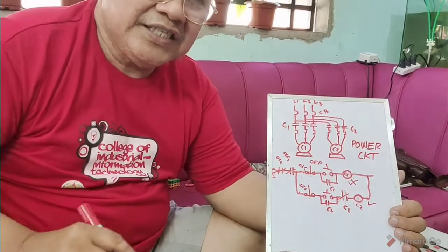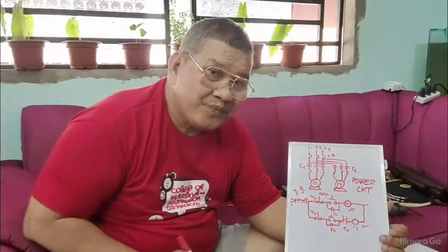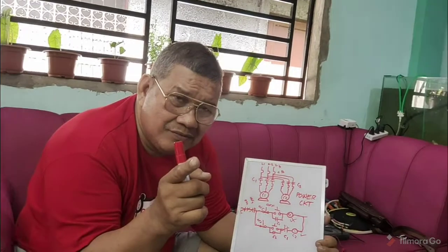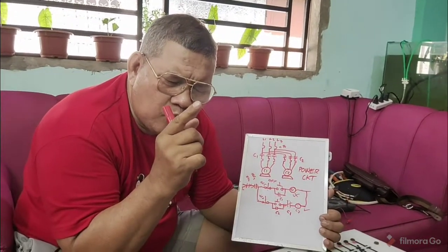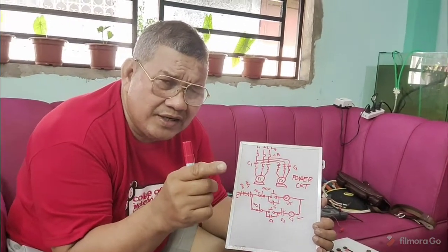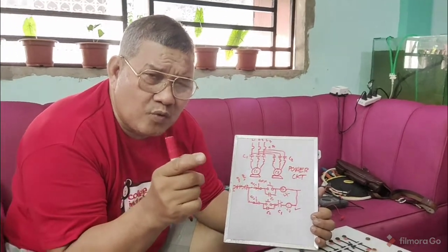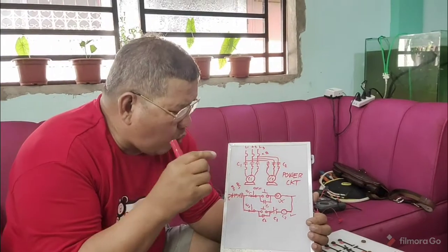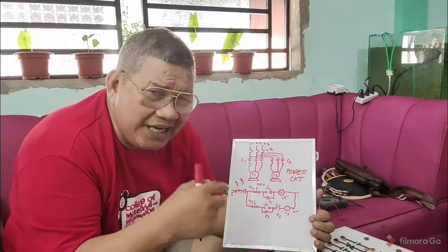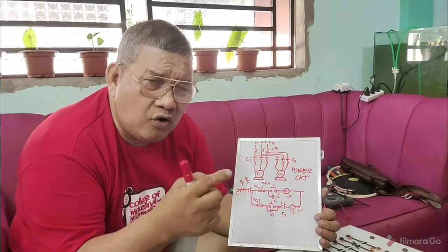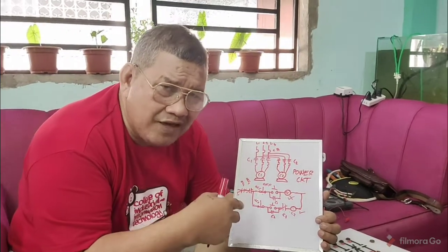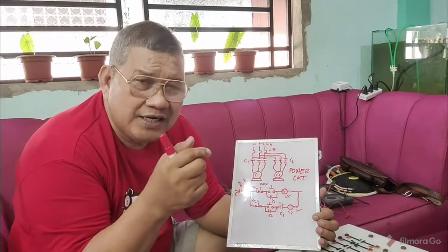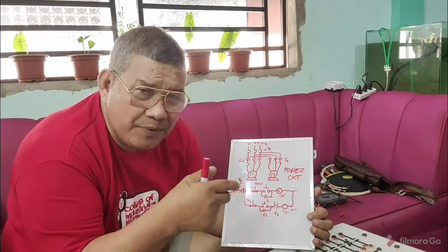So this is sequential control. There are two conditions. Okay? First condition, conveyor number 2 will run when conveyor number 1 is running. Another condition is when one of the motors, or any of the motors, is overloaded, both of them are disconnected or not operating.